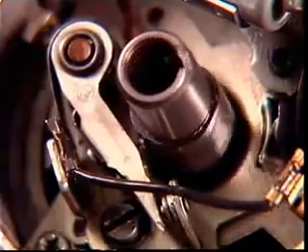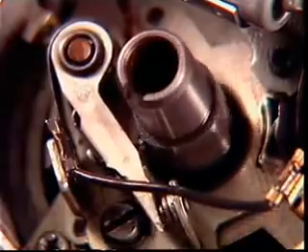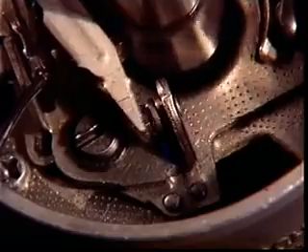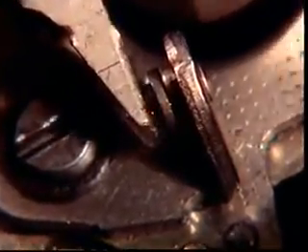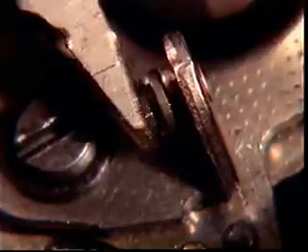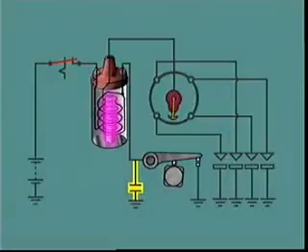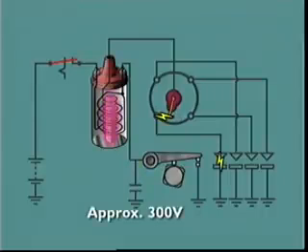Opening and closing the contact breaker switches the primary current off and on. When the contacts begin to separate, the primary current tends to flow on and produce an arc across the contacts. The capacitor absorbs this surge of inductive current by providing an alternative path in parallel with the opening contacts. The capacitor charges to the peak value of the primary winding voltage.